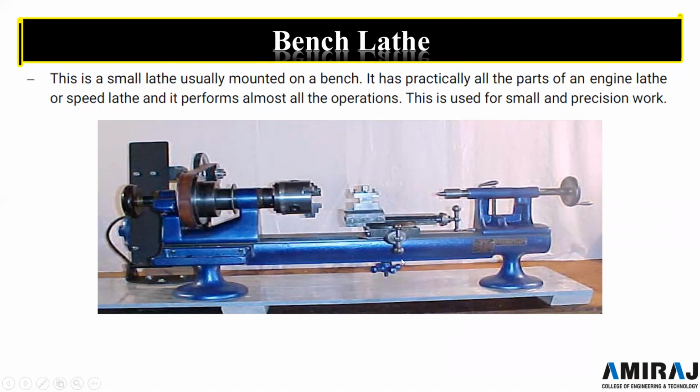It has all the parts. You can see here that there is a tailstock and headstock. This belt and pulley drive is there for rotation of the chuck or the spindle, and this is the carriage over which the tool post is mounted, and this is for the cross slide and longitudinal slide as well. This is used for small and precision work.